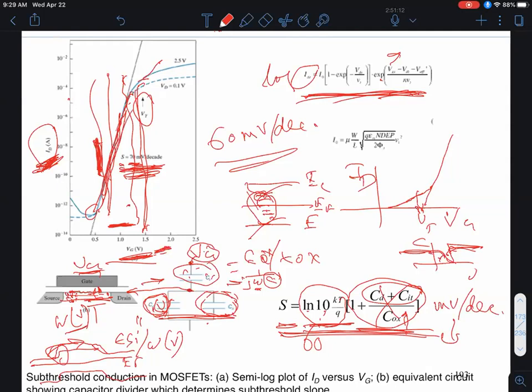And the question, of course, is why? Well, that turns out to be ultimately because of the Maxwell-Boltzmann distribution. Okay, so basically what happens is, if you look at this band diagram, we know that the carrier concentration, you have more carriers at lower energy, and as you go up to higher and higher energy, you have fewer and fewer carriers, which basically scale as e to the power minus energy over KT. That's your Maxwell-Boltzmann classical limit of your Fermi-Dirac distribution function. So these high energy carriers can go over this barrier, even in the off state, okay? And the way you can modulate the leakage will give you the subthreshold slope, okay? So people sometimes jokingly will call it the tyranny of Boltzmann, okay?